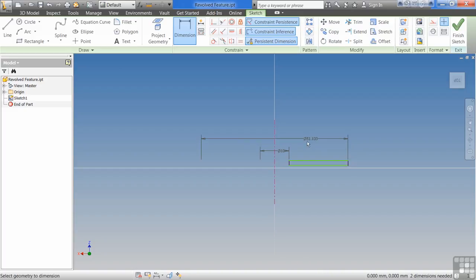And you may say, wait a minute, what just happened there? What happened was, as soon as I click on that center line to do a measurement, Inventor understands that center line is supposed to be the center of something. It's going to let us use the overall diameter of this part to give it a dimension. So if I'm making a sprocket, let's say, I know that this sprocket needs to have an overall dimension of 50 millimeters. The inside shaft is going to be 10 millimeters. So it allows me to create this. So the last dimension I'm going to give it, be 5 millimeters thick.